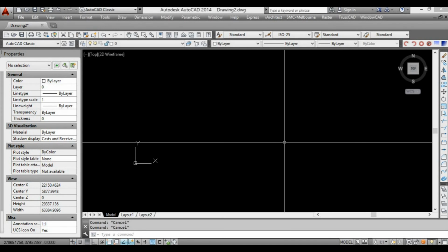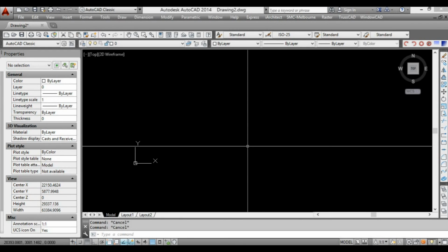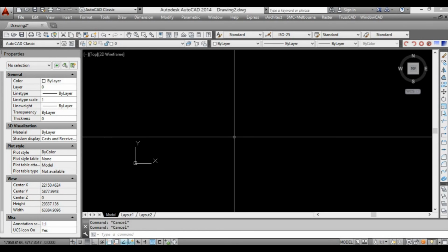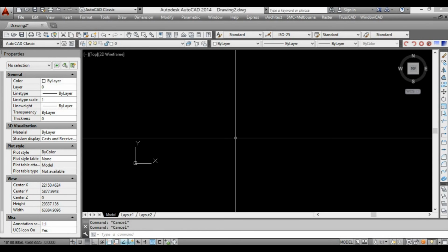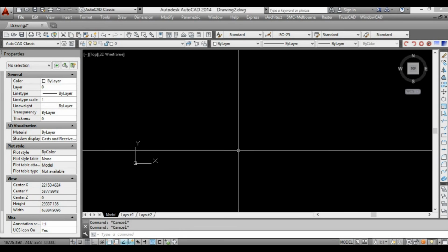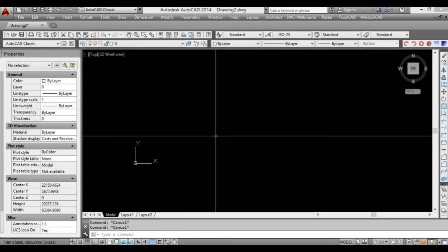In this lesson, the last command we're going to look at for drawing is called the polyline. A polyline is basically the same as a line, but when you're drawing a series of lines, they're all connected together using a polyline, and a polyline can even connect arcs to it. This can be very useful in many areas. We'll get into that, but we'll start the command first.